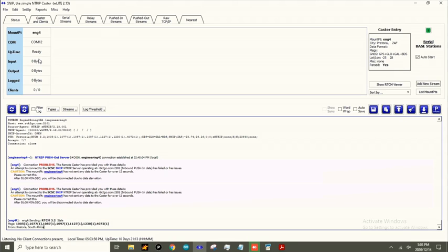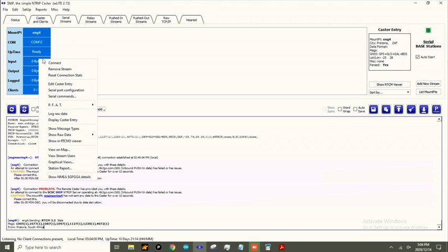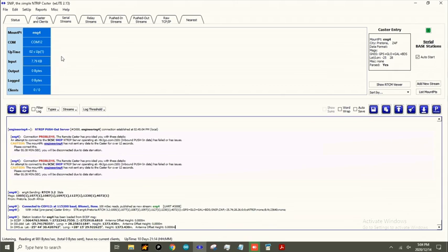So once we have the serial input stream configured, if we right click on the entry, we can now say that we wish to connect to that serial stream that is available. That's the GNSS receiver. So once I click connect on that serial stream, you will see that it's starting to receive input data. Normally it will run a brief analysis on the data stream once we first create it, but the format stays largely unchanged, so it's nothing to worry about if you see that.